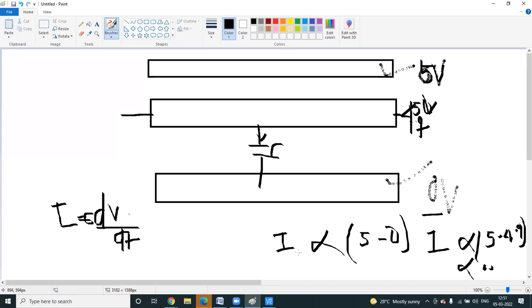So out of these, in which one is the current less? That will be good for this unwanted current. So if you connect it to VDD, this current will be less. Understand or in doubt? So which one is preferable? You connect it to VDD if this net is connected to PMOS. If this net is connected to NMOS, then you connect it to VSS. Understand or any doubt?